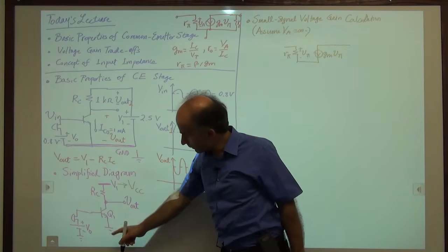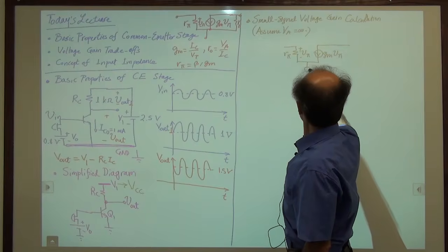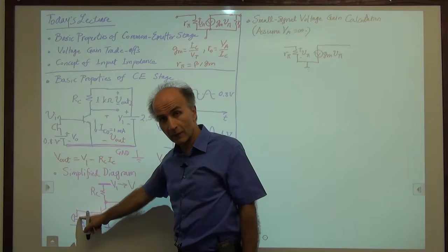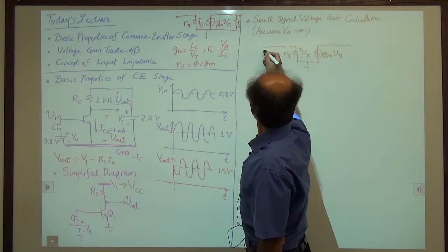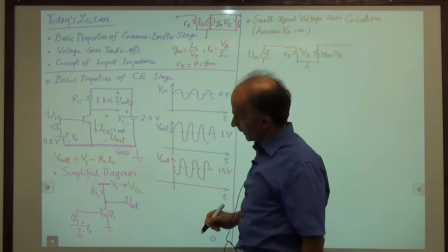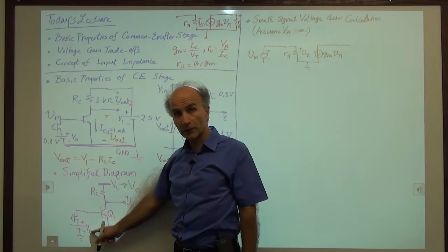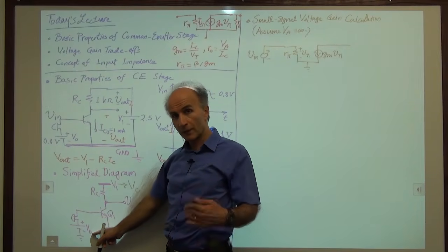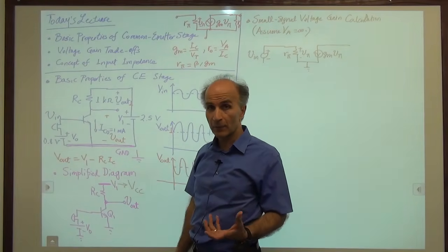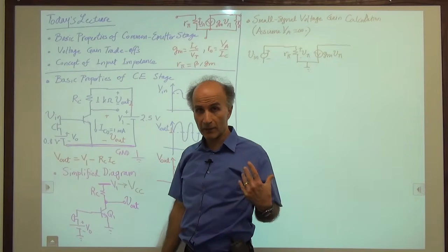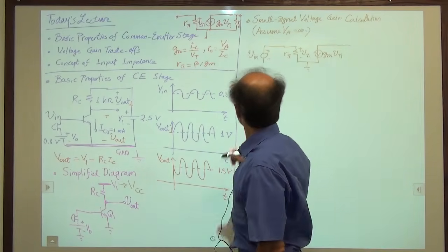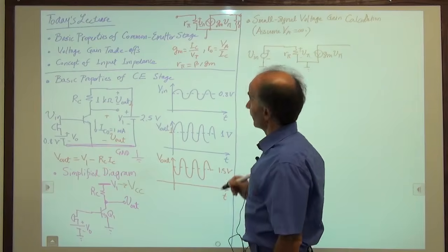We see that the emitter goes to ground. So that's just the ground. The base goes to a voltage source representing the microphone. So here's a voltage source, which we call Vin. And then we have a bias voltage. Remember that when we draw the small signal model, the bias voltages, all the constant voltages, become zero because they don't change. The small signal model represents changes. These voltages don't change, so their change is zero. So that is replaced by a zero, and we go to ground.